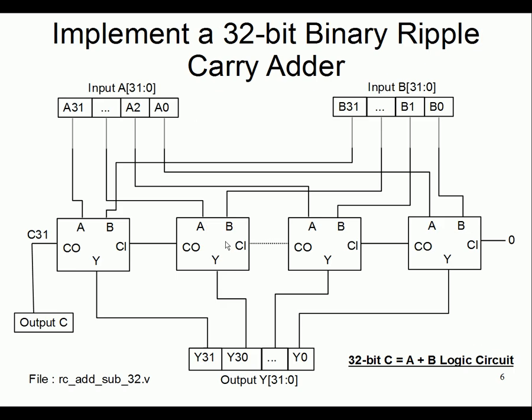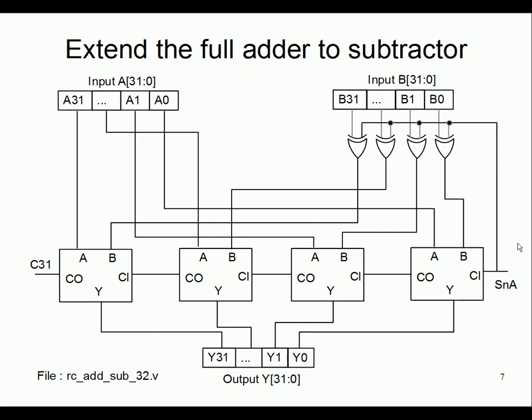That module we instantiate, connect it, and collect the 32-bit output of it. The first stage carry in is tied to 0, logic 0, like 1'b0, so that will be grounded. Once you do that, we convert it accordingly to the subtractor.